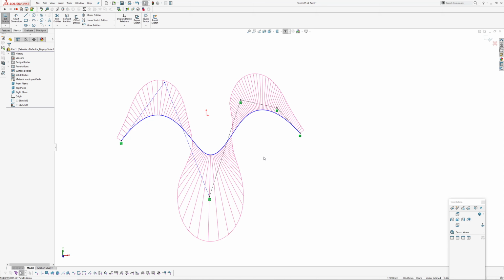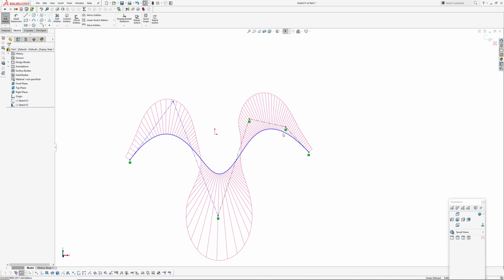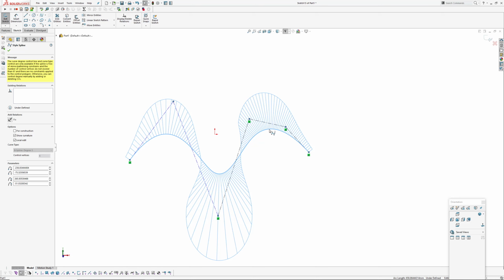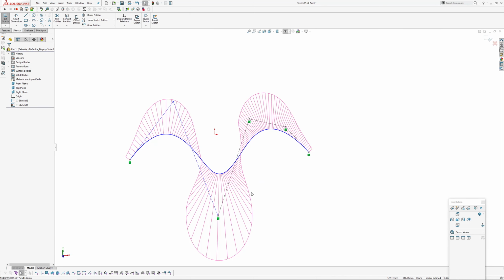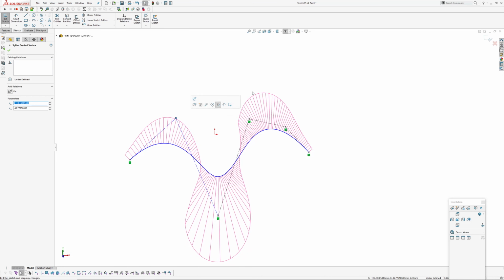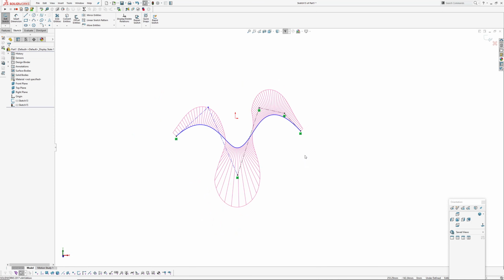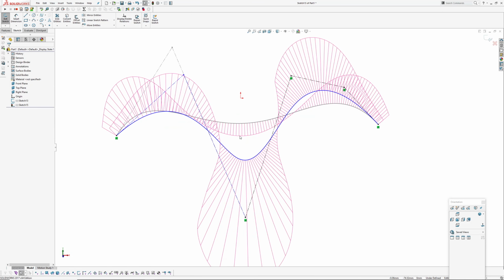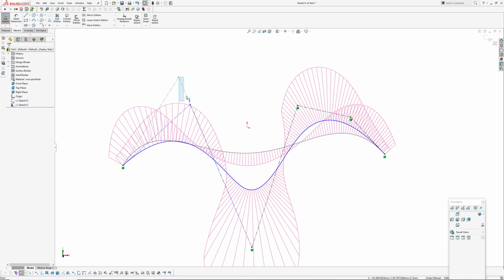So basically the highest continuity you can have internally in a multi-span curve is the multi-span curve degree. So in this case, you see there it says next to the cursor 3. Degree 3 minus 1 is G2. So that's curvature continuous, the best you can get as far as internal continuity. That's why you're seeing this sort of peak here. But as you noticed, I bring up my background curve again. If I match these CVs up, oops.